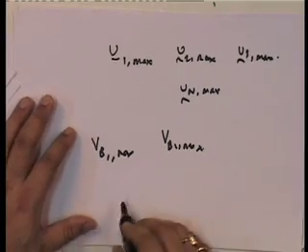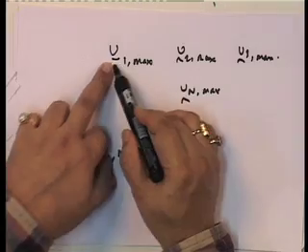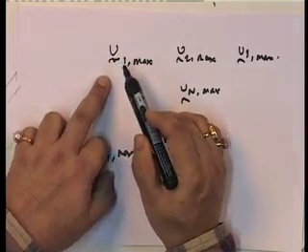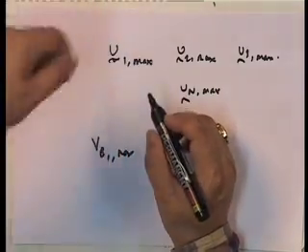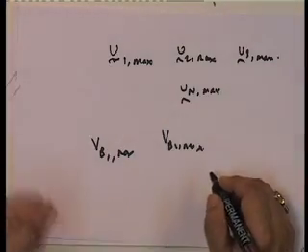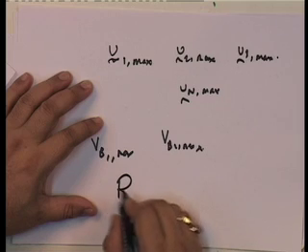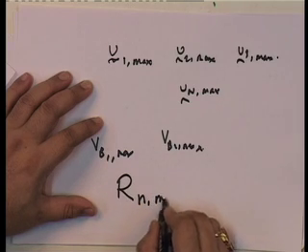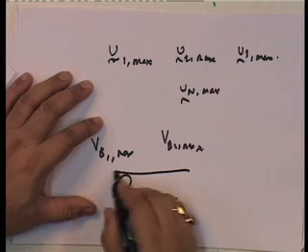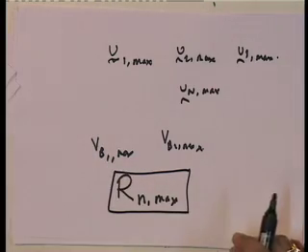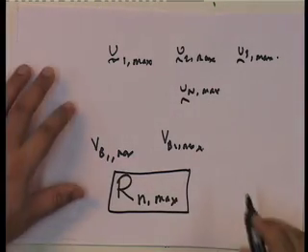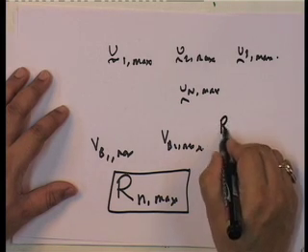In this particular vector you actually have particular displacements, let's say top story displacement, which you can read off. So for any response quantity, I'm getting Rn, the peak response, because I'm using the response spectrum.